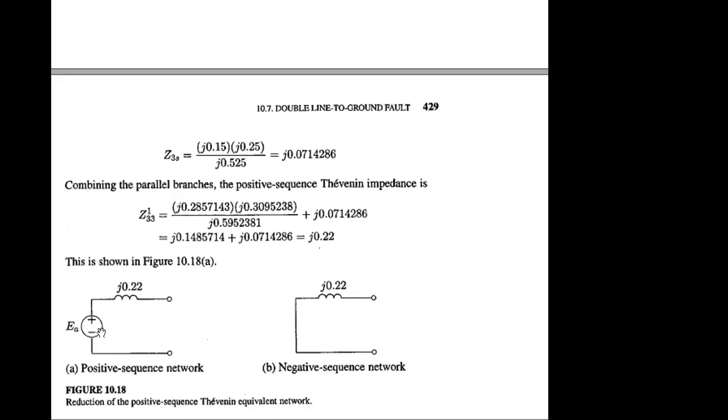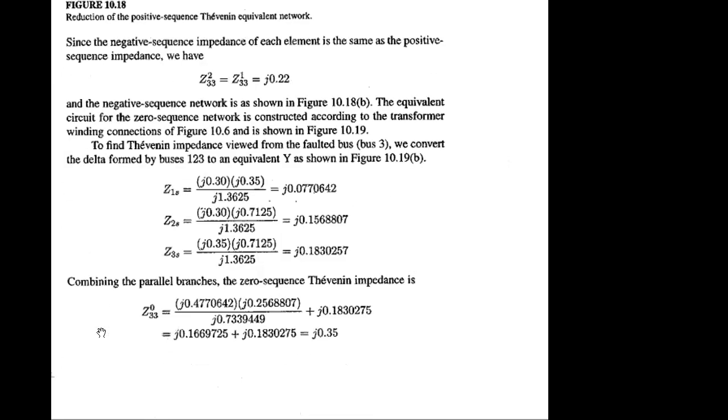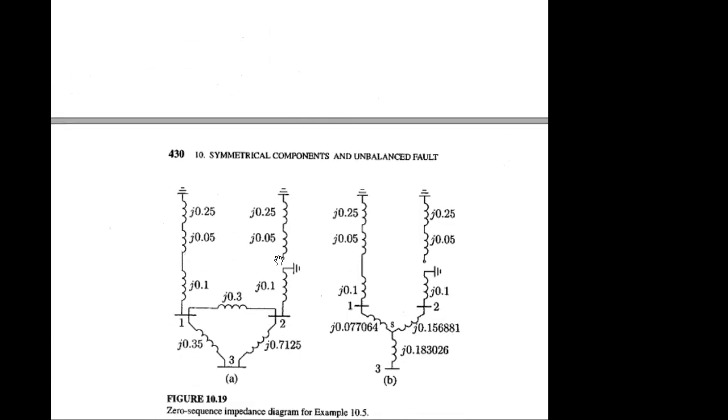So if we just think of the regular scenario, it is the positive sequence circuit. If you just say three-phase circuit solution, it is better to mention that you have solved the positive sequence three-phase circuit up to now. You have not dealt with the negative sequence or zero sequence. From now on, you have to consider those as well. For the zero sequence scenario, you have to consider the transformer circuit. If it is regular, you don't need to bother about this configuration, but as it is zero sequence, you have to think of that.